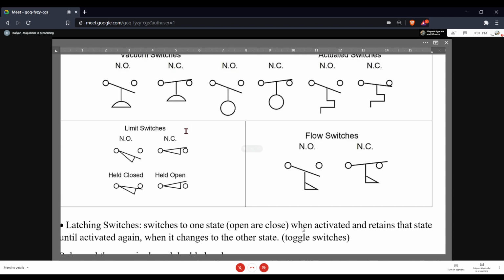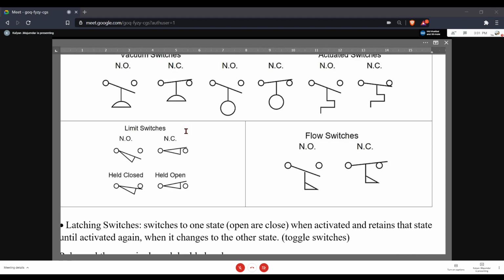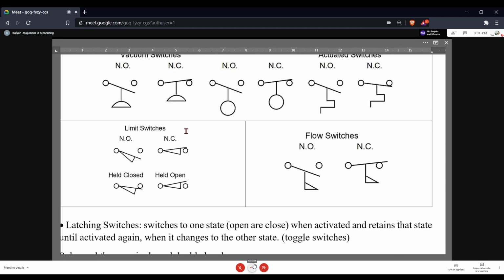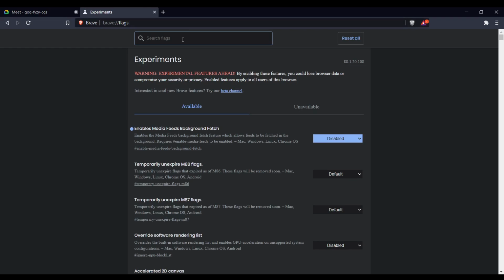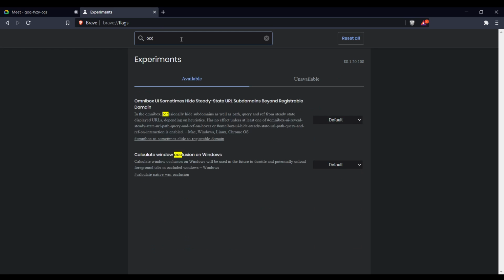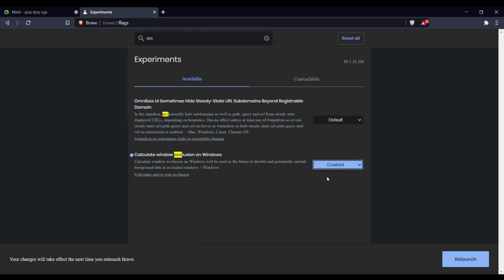So all these sensors are referred to as limit switches. Limit switches are basically devices that sense the position of an object. So in all these cases, you're basically sensing the position of an object. A door can have two states, it's either open or closed. So these are sensors which sense position and give a two-state output. If the door is open, you get one state from this particular sensor. If the door is closed, you get a second state from this particular sensor. Limit switches and proximity switches are similar devices which sense position.